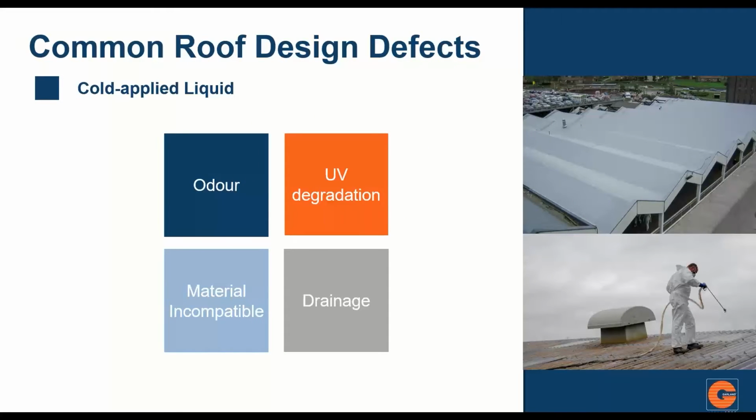And cold applied liquids. Some cold applied liquids have a terrible odour. So you don't want to be specifying a really bad smelling liquid if you're in a hospital and you're doing a repair project directly underneath their air intake. If you have a horrendous odour in a very sensitive area in a hospital, you're going to inevitably have to evacuate it. And despite many of the odours not actually being harmful to humans, the foreign smell starts to concern people. So we always need to be concerned about the odour in terms of the design and the application where it is.